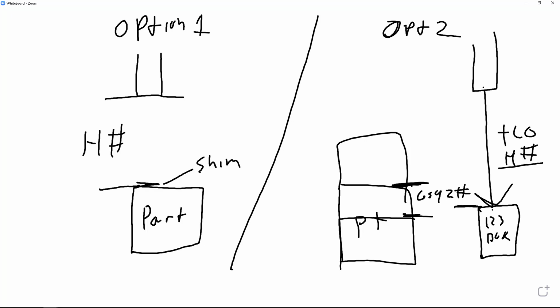These are the two main ways we're going to do this in the shop until we get into the probing system and the tool presetter. So that's where I'll leave you for now as far as how to set up the tools. Again, you could set up all the tools to the part height, and that's a quick way to do it.